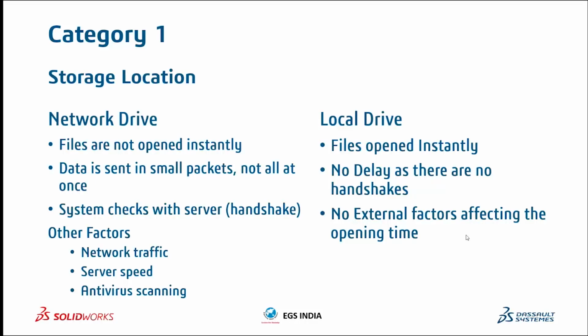What is going to happen is the data is going to be split into smaller packets, file by file, and it's going to come to your RAM. And the problem with the network drive is, for each packet sent, the system is going to check if the connection is okay or not, if the file is okay or not. These are called handshakes between a system and a server. So all of this makes it hard for SolidWorks to open a large assembly with n number of references directly into your RAM. So this is the first major factor.